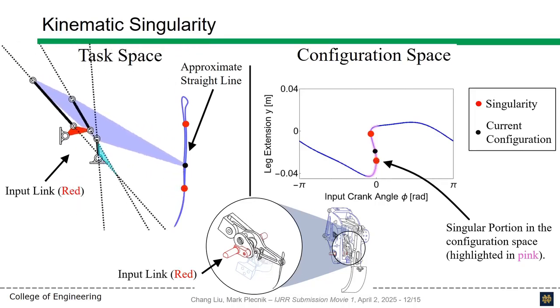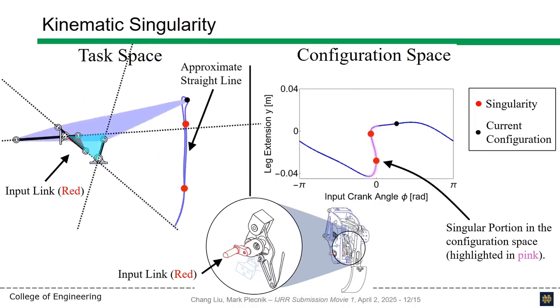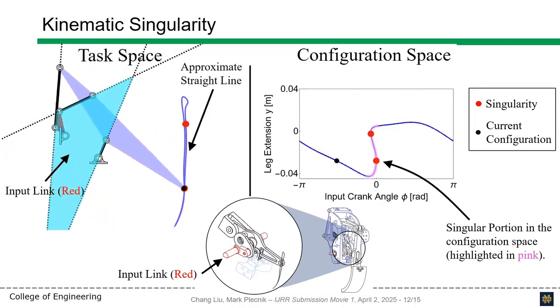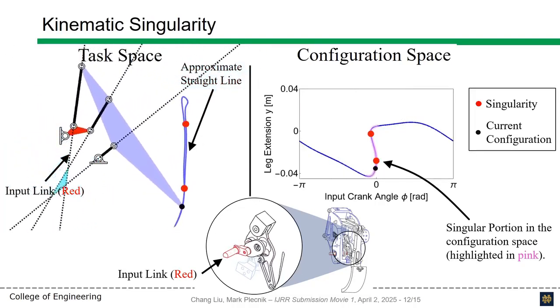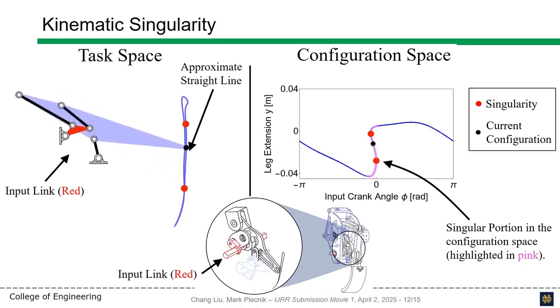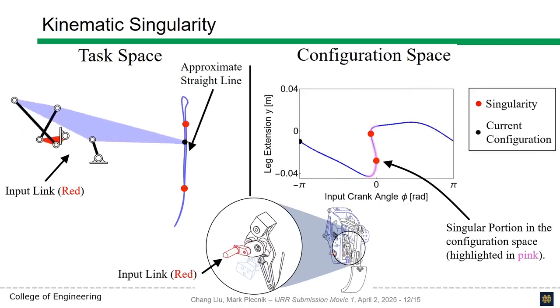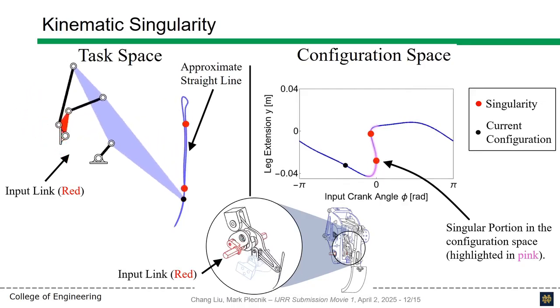Over the near singular region, the mechanism gains extra mobility, allowing the foot point to travel upwards, despite the input link being fixed. This extra mobility over upstroke enables automatic contact detection and reaction as vertical ground forces move the mechanism out of the singular region.